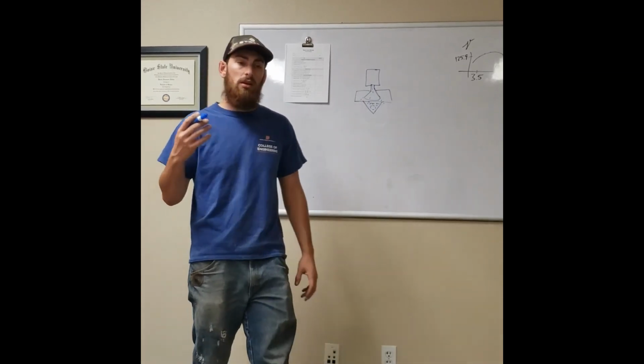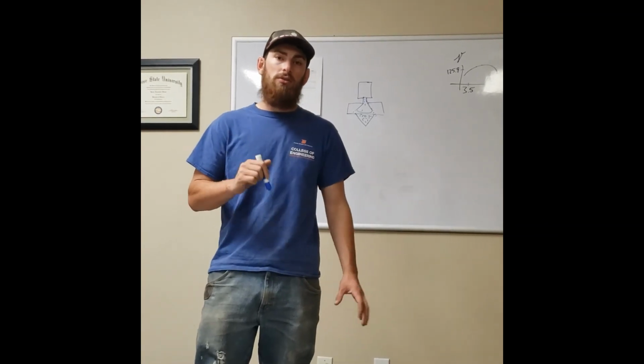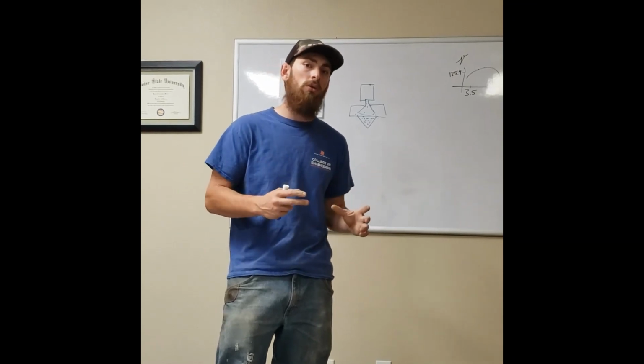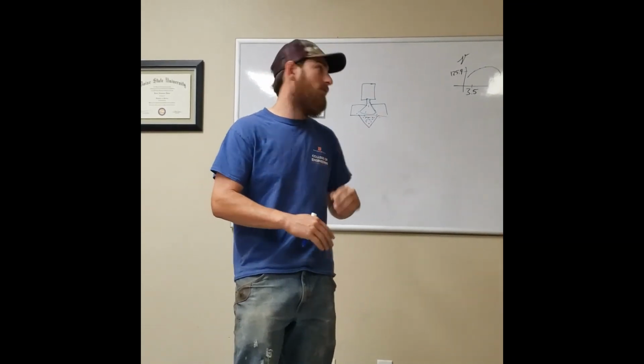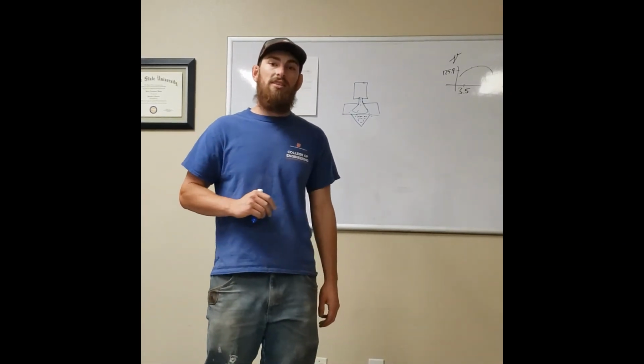I'm going to take the material that I dug when I created that hole and dry it, so I'm going to get a moisture content on it. Based off of how much material I took out of the hole, I take that same mass divided by the volume I calculated from the sand calculation, and that's going to be the sand cone.